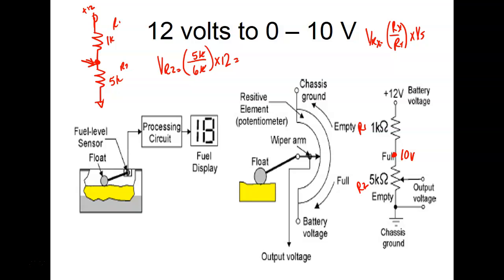Now, what's nice about this formula is that most of the time in DC, you'll say, okay, I've got a 5K and a 10K, and I put 12 volts across the circuit. What would the voltage drop be? You would say 12 volts divided by the total resistance gives me I, then I take I and multiply it by my resistors, and that gives me the voltage drop. But then I'd say, let's put 15 volts across it.